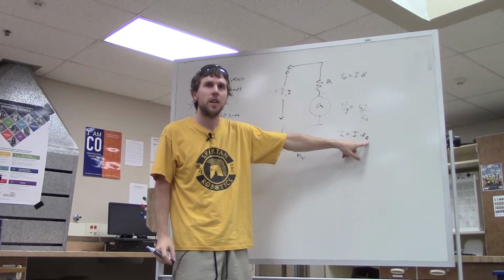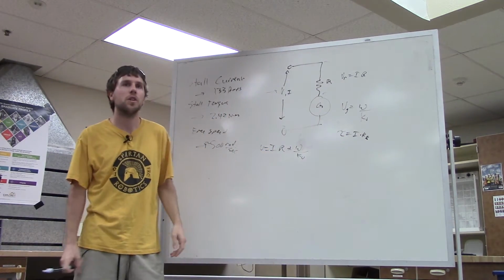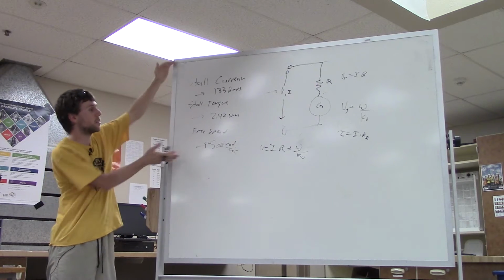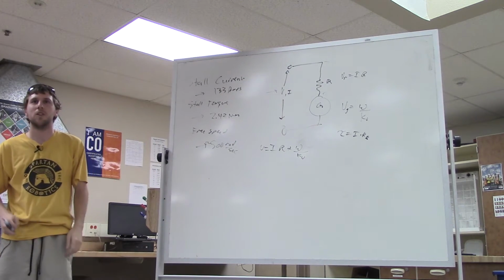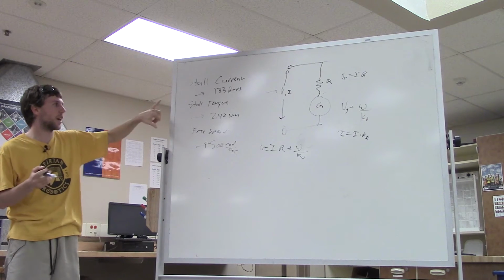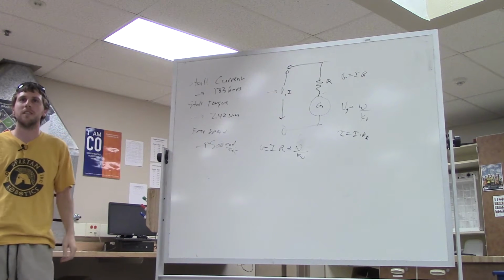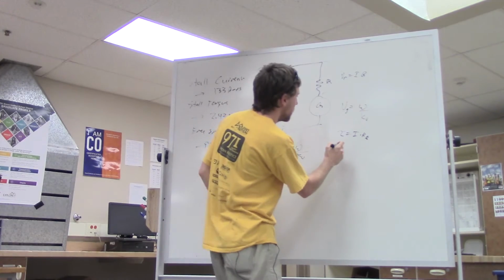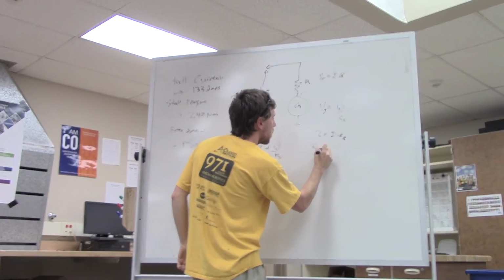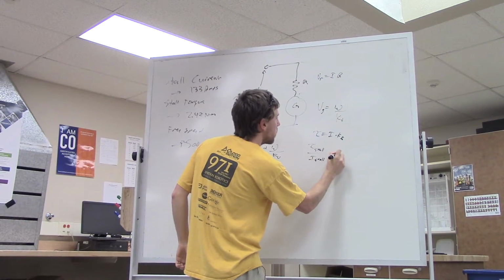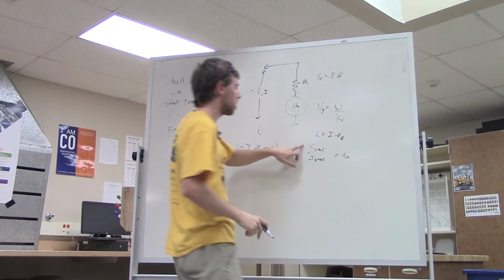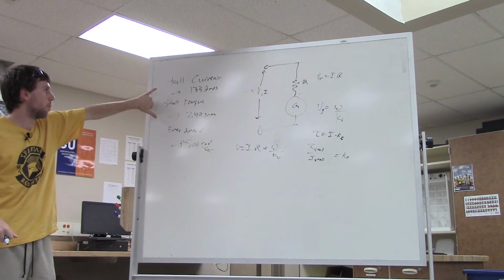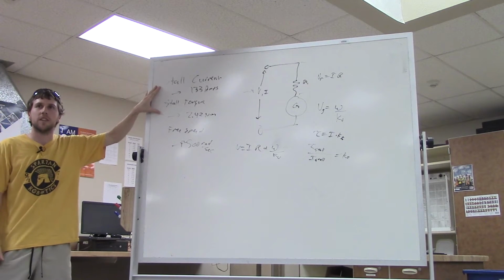But say we don't know KT, but we have specifications for a motor. So if we can find a torque and a current, we can compute KT, right? So this is the specs. This is actually enough information to compute those. So what torque and what current do we use to compute KT? Yep. So it's the stall torque over the stall current, which, if someone has a calculator handy, we can compute. You just divide the two and you get KT.